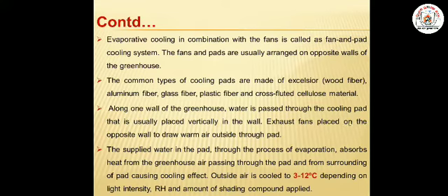Exhaust fans are placed on the opposite wall to draw the warm air outside through that pad. The supplied water in the pad, through the process of evaporation, absorbs the heat from the greenhouse air passing through the pad and from the surroundings of the pad, which causes the cooling effect due to the evaporative cooling phenomenon.